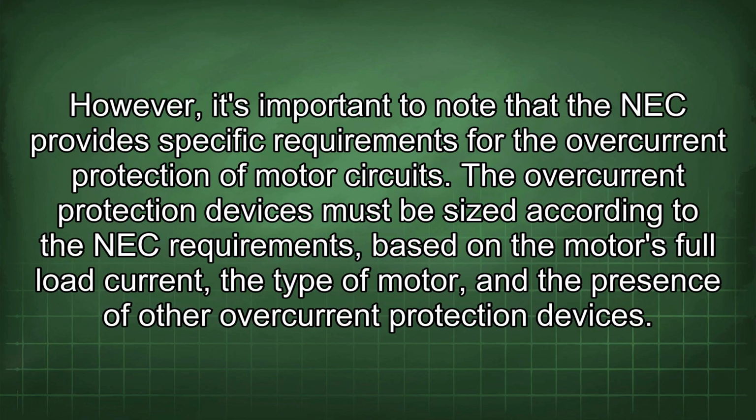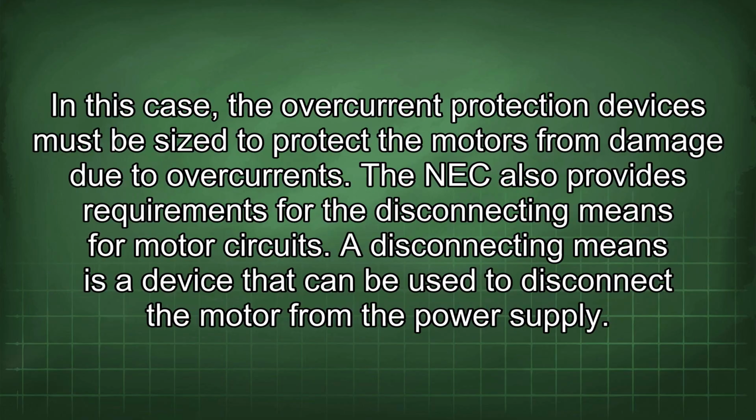However, it's important to note that the NEC provides specific requirements for the overcurrent protection of motor circuits. The overcurrent protection devices must be sized according to the NEC requirements based on the motor's full load current, the type of motor, and the presence of other overcurrent protection devices. In this case, the overcurrent protection devices must be sized to protect the motors from damage due to overcurrents.